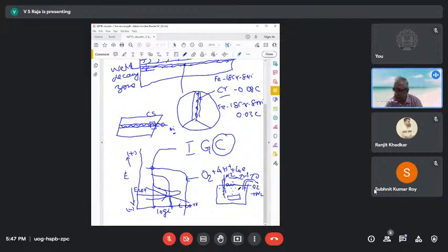Now, as you said rightly, the amount of oxygen required to maintain the passivation is very less. You don't need that much oxygen because the passive film is already formed. So even if the oxygen is very low, the passivation remains, no problem. But now, if you make a scratch, the bare metal is exposed to the surfaces.